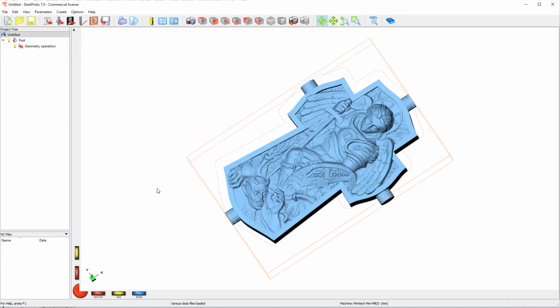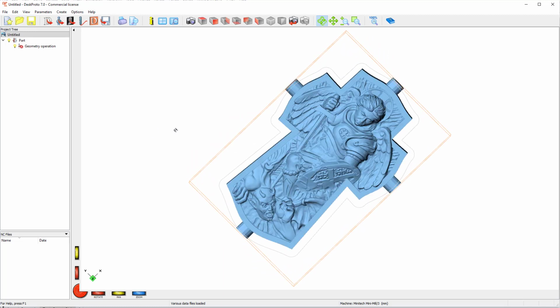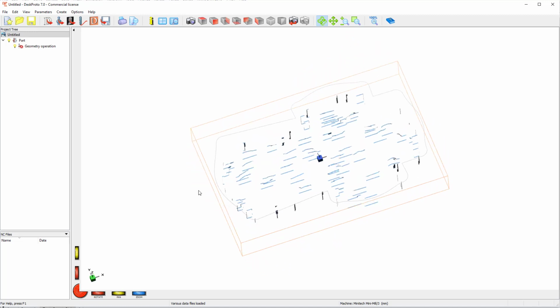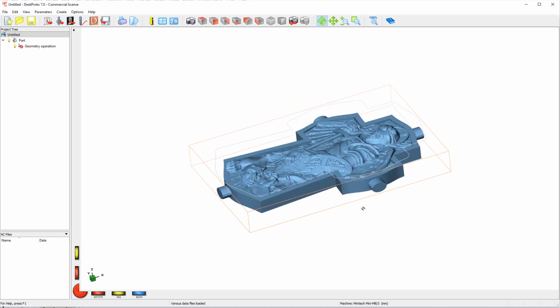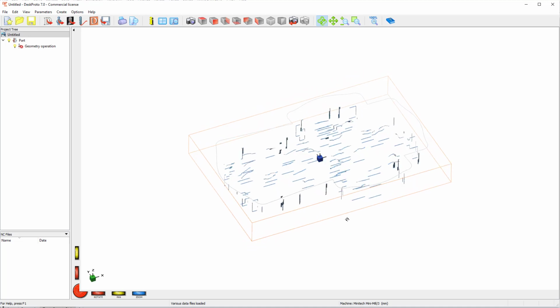And what that does for us in many cases, when you bring in just the geometry on its own and you then bring in a cutting curve afterwards, sometimes your supports are not going to be in the same position as your outside cutting curve, and the default cutting window is not big enough, and then you have to go in and edit and create the window a little bigger. So always bring in an outside cutting curve anyway, so that it expands the size of the cutting window for us to the size of the outside curve I intend to cut with. So we've got the geometry in there that we want to start working with.